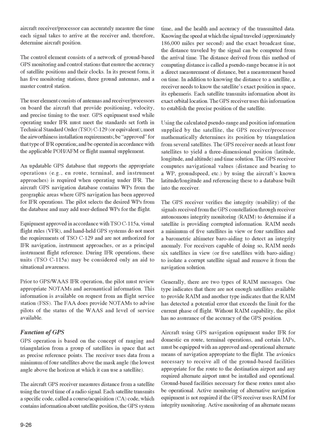Prior to GPS/WAAS IFR operation, the pilot must review appropriate NOTAMs and aeronautical information. This information is available on request from In-Flight Service Station, FSS. The FAA does provide NOTAMs to advise pilots of the status of the WAAS and level of service available.